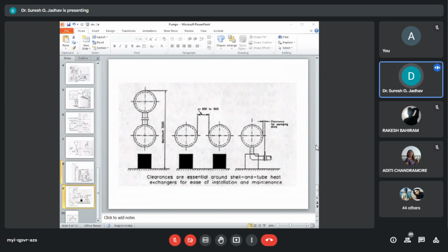Fixed tube heat exchangers. In these fixed tube heat exchangers, exchangers with completely enclosed tubes are mainly used in clean services. Cleaning can be done by flushing through the tube side and the shell sides. Clean out connections are provided in the piping between the exchanger nozzle and block valves.